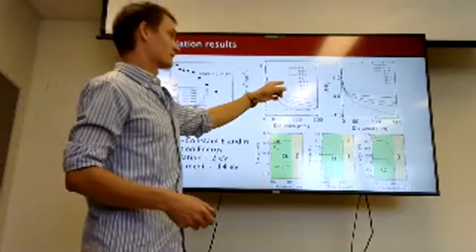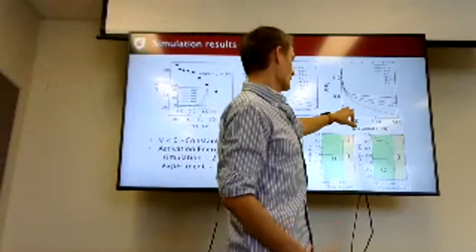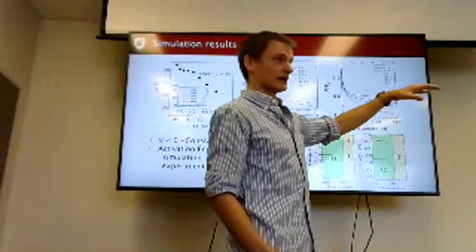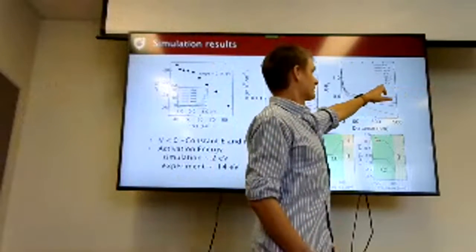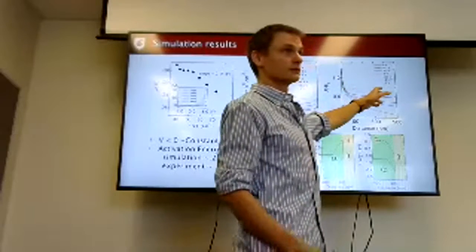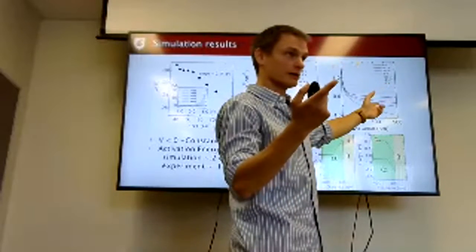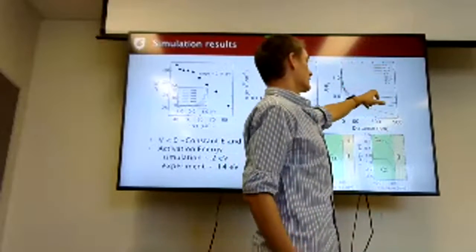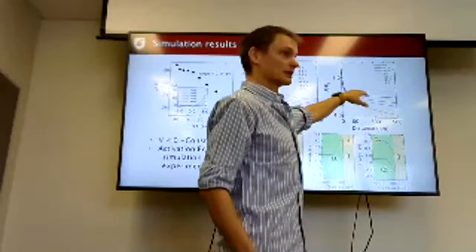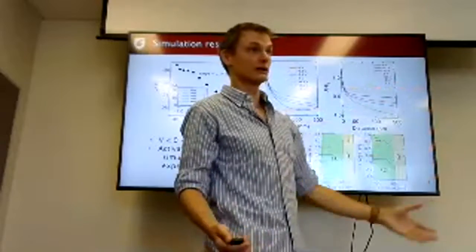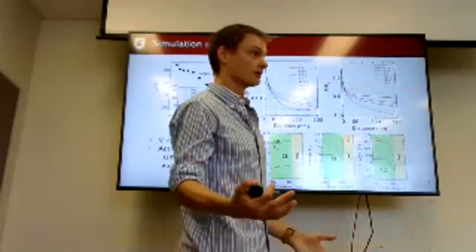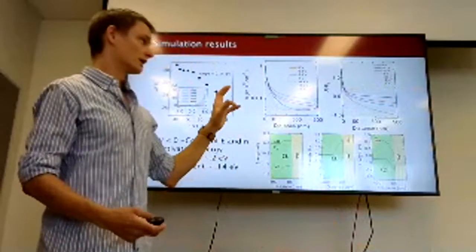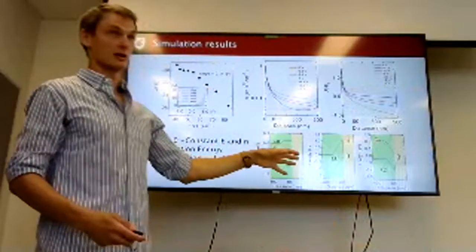Then we can look at the electric field under positive and negative bias. Under negative bias, we have a constant electric field. If you integrate a constant, you're going to get a straight line, right? And that's what we see in the voltage. Under positive bias, we see a rapidly changing E field, which if you integrate again, you get back to the power law. So we think we've included the relevant processes in this model.